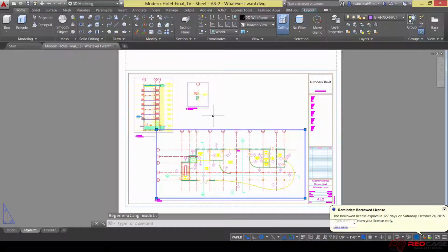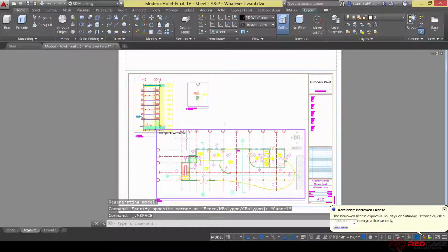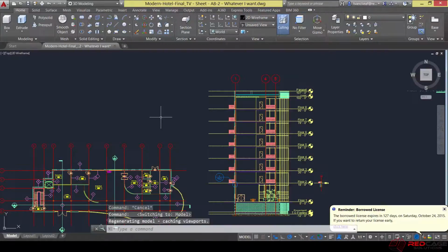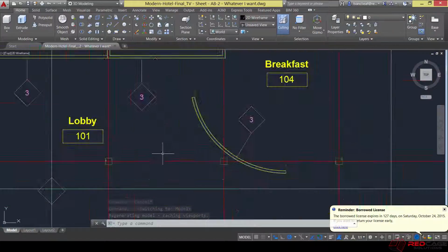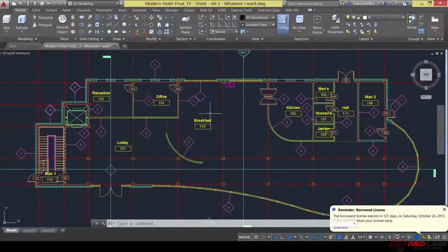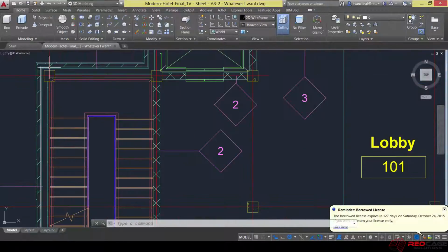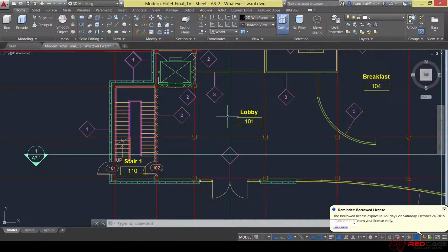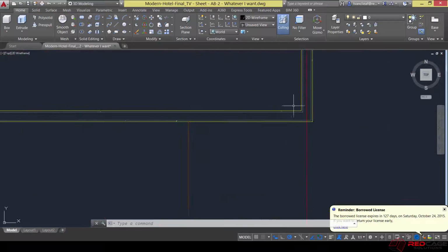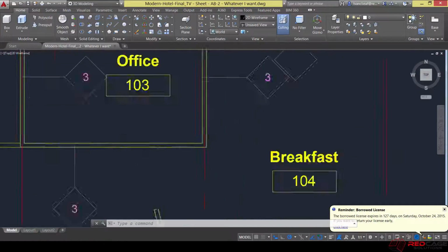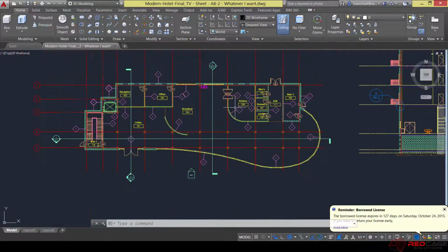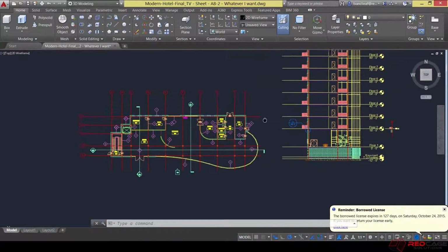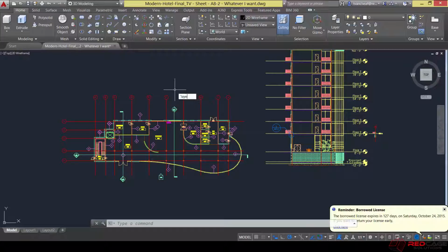And you'll notice that I've got some viewports here that I can access the same way that I always have in AutoCAD. And if I go into my model space, I've got those 3 views set up here with a very decent layer setup. It's done this nice. I can tell the difference between the annotations and the walls. You're seeing the assembly components of the walls as well. And even if you didn't set up an export setting, you could change this quite quickly just going into your layer manager.